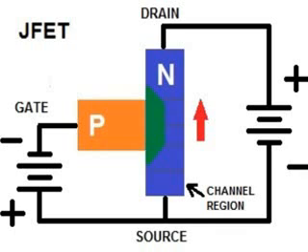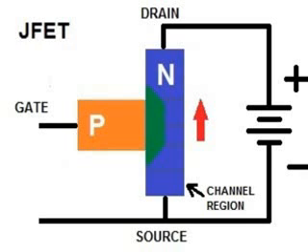When you apply a voltage on the gate, the drain current will go to some set value that corresponds to that gate voltage. If you remove that gate voltage, the depletion region will remain there for a while, and the drain current won't change for a little while until this so-called capacitor discharges through leakage current, and the transistor inches back towards saturation, and there's no source drain resistance anymore.